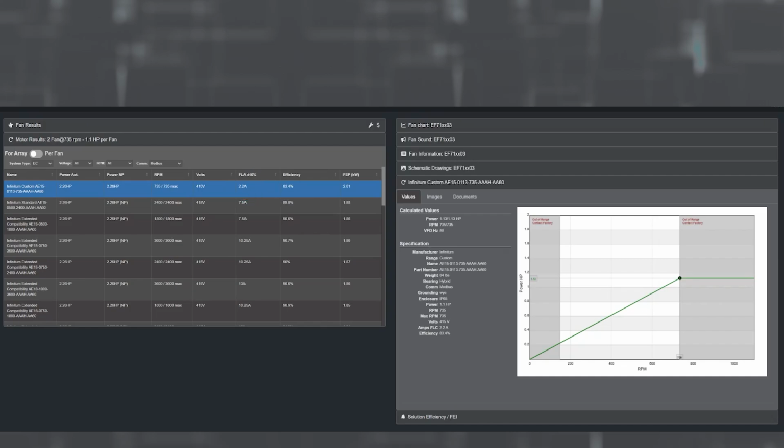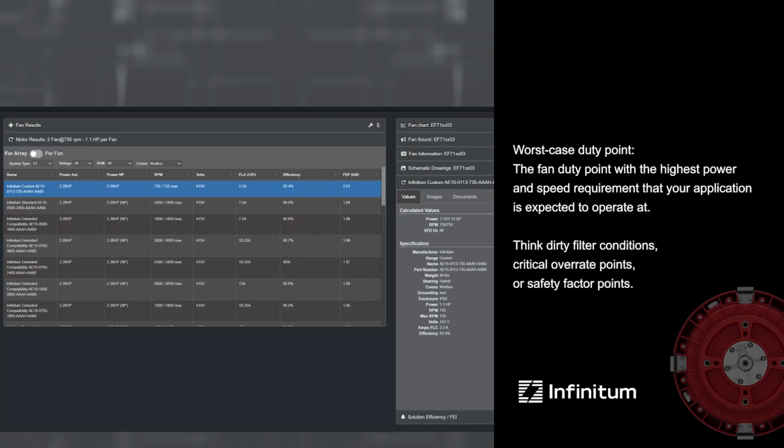Custom nameplating is done entirely in software. Same motor, different programming and label. The benefit is a lower FLA in the nameplate, which can simplify electrical design and panel sizing. Trade-off is reduced headroom. If the installed system needs more speed or torque than the duty point allows, a custom nameplate motor has no buffer, as we see here on the curve. Our general recommendation, always select to your worst case duty point. If you're unsure, the standard motor gives you the highest safety margin.